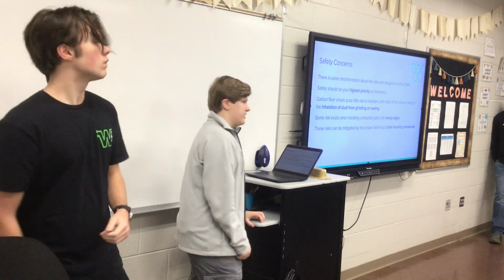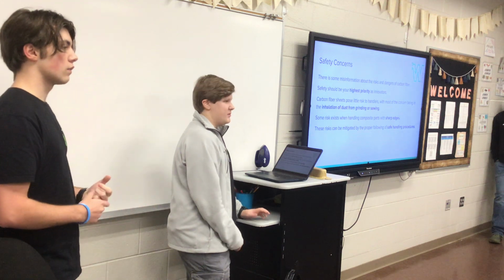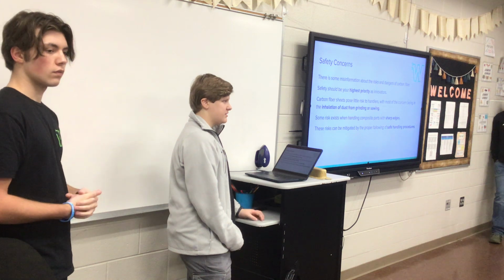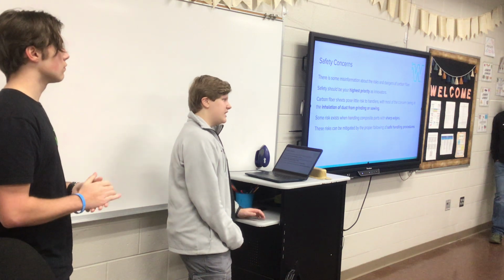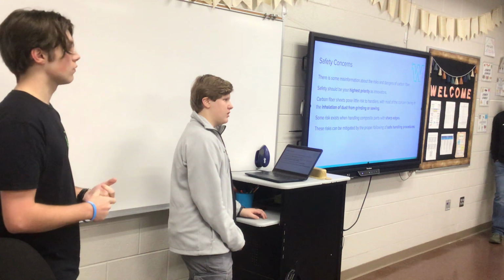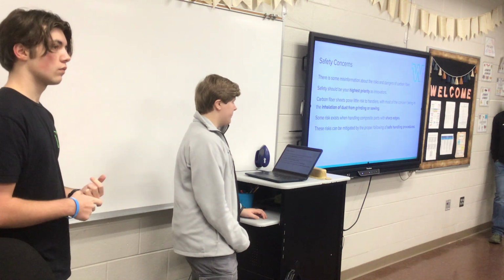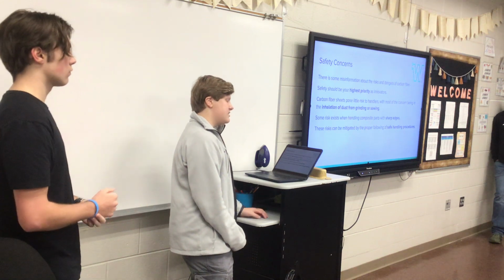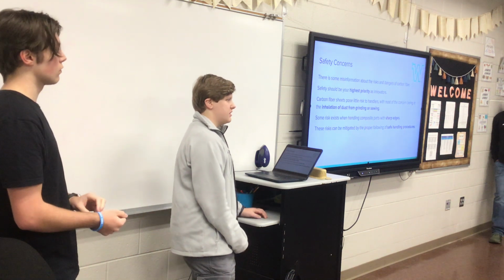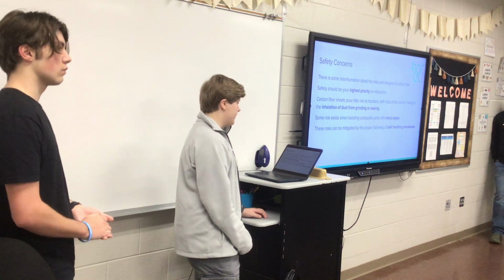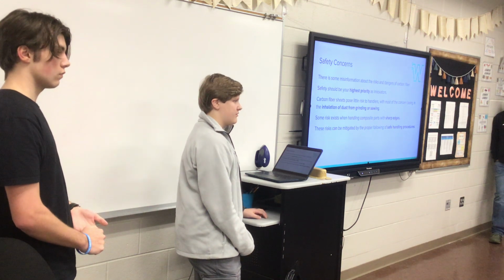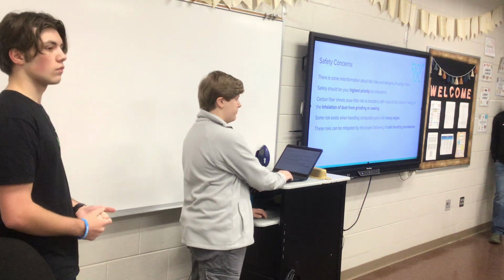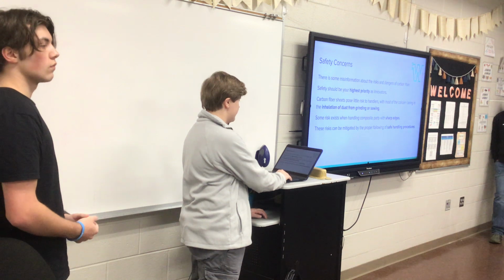So looking around at what it says on Chief Delphi, there's just a lot of misinformation about how dangerous it is to handle carbon fiber and other composites, which it's not super high risk as long as you're following proper precautions. So obviously safety is always going to be highest priority, but the main risk with these is if you're sawing them or grinding them, because the dust can be very abrasive and harmful to breathe in. And then also, sharp edges have a risk. But with proper handling procedures with these, you can almost entirely lower those risks.